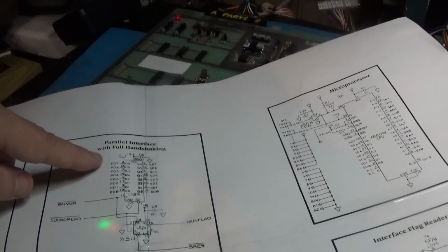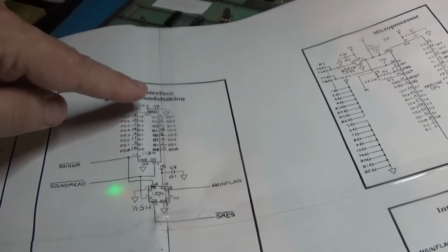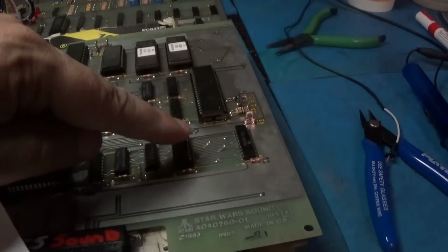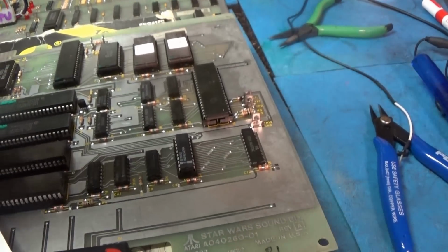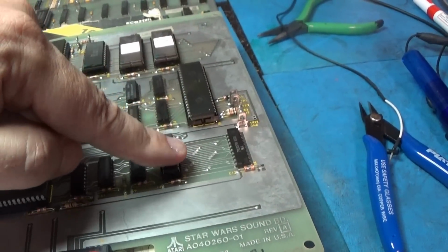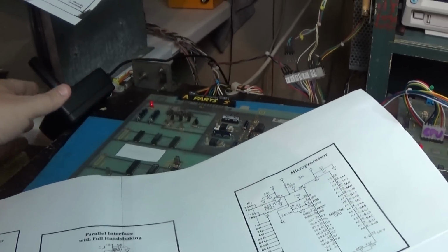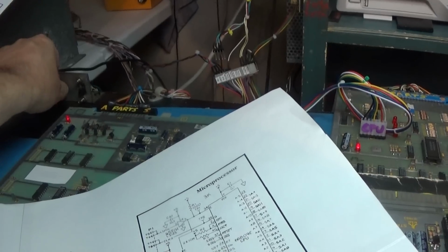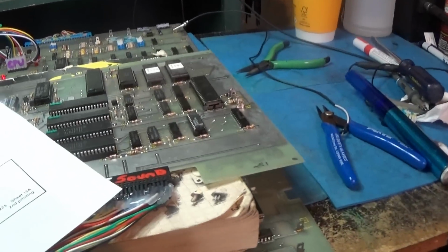Well, I was looking at the signals coming into here and out of this, and one of them was floating. It was floating, and then it would go high, but it wouldn't drive low on this guy. So I just replaced this, and I believe that we have fixed our problem. Good 5 standing by. Yeah. So just that chip right there.